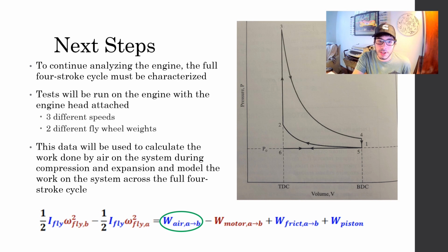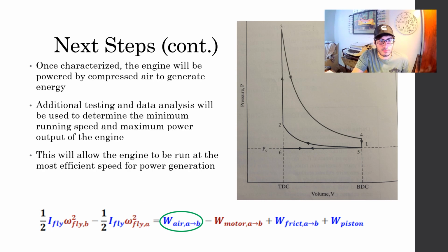the integral of PdV. The experimental values should differ from the calculations generated from the model, but they should be comparable. With no energy added during isochoric combustion and exhaust blowdown, it is expected that the work from the compression stroke should be about the same as the work from the expansion stroke.